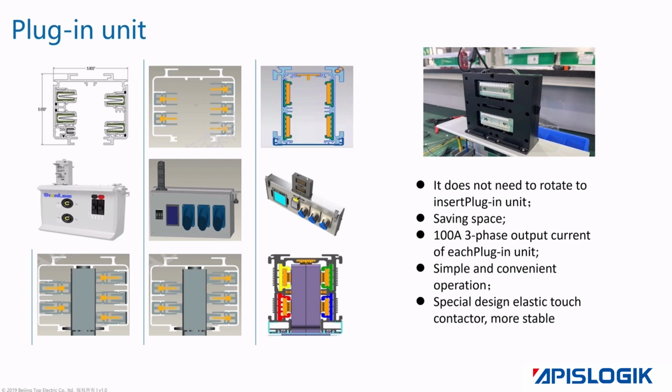The second type uses I-type copper bars, and the plug is U-shaped. After insertion, it is rotated 90 degrees and locked. Topline G series bus bars adopt I-type copper bars, deployed on both sides, and the tap-off unit contacts are pressed on the copper bars to take power.